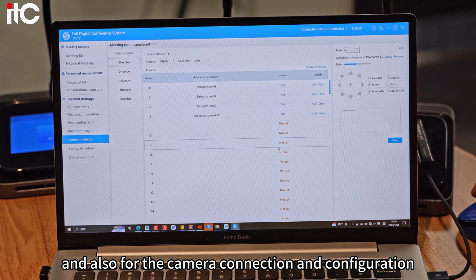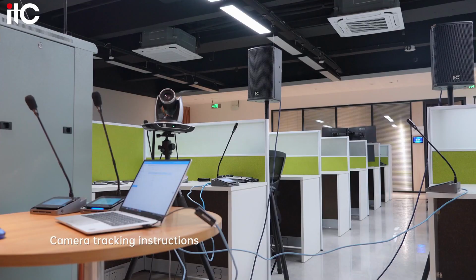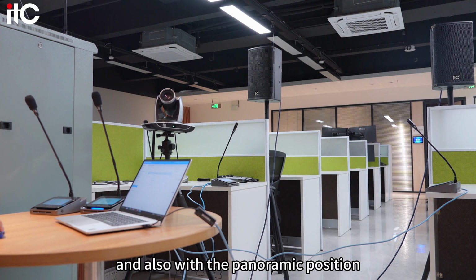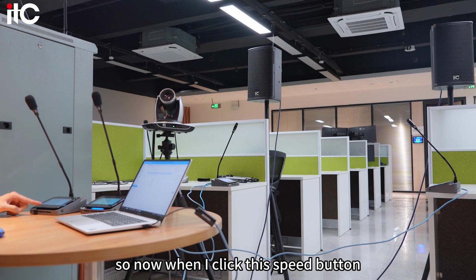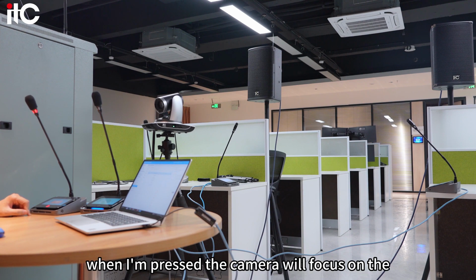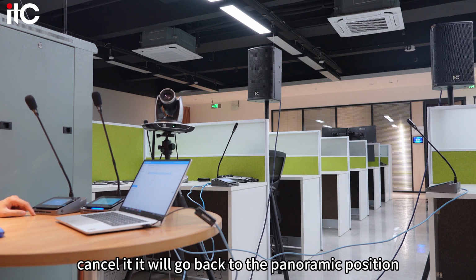And also for the camera connection and configuration, users can directly connect the camera by 485 port. So now is the effect of the camera tracking system. For now, I have already set the positions of all of the microphones and also the panoramic position. So now when I click this speak button, the camera will automatically track to the delegate units, just like this. When I press, the camera will focus on delegate 1. When I cancel it, it will go back to the panoramic position.